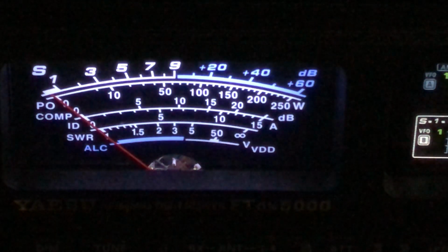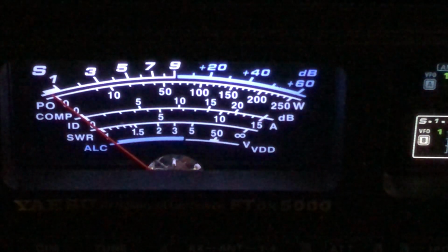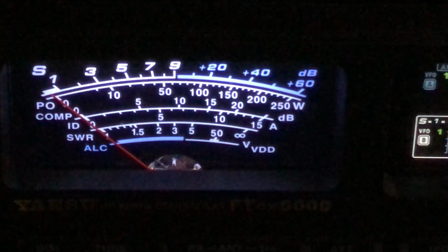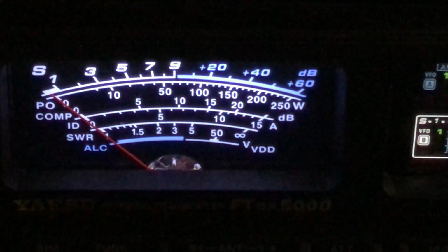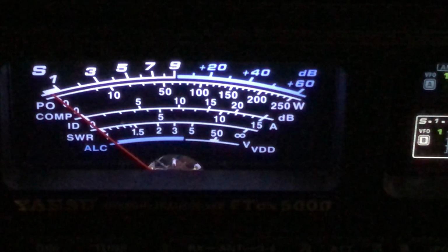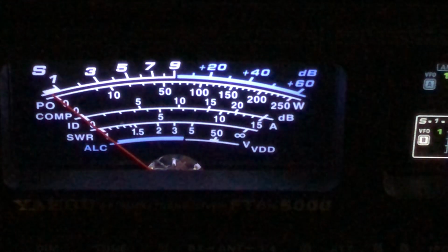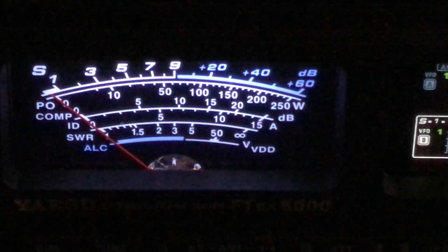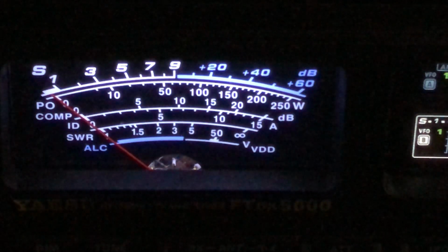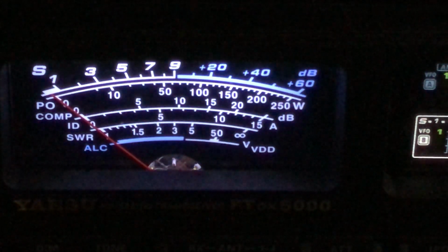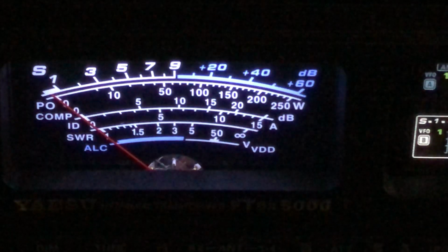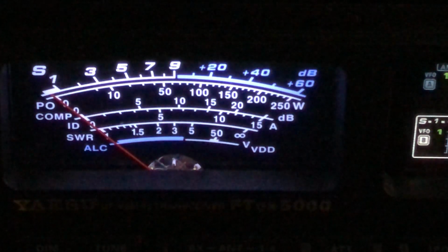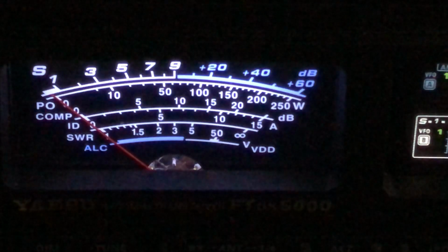And in my background working with radios since the 1970s, I can tell you that with a D'Arsonval movement, you generally calibrate it in the middle, which in this case will be S9, and they won't be perfectly accurate on the low end and the high end. So you calibrate in the middle, and you would expect it to be a little bit off on the low end and high end. It just has to do with the meter movement.